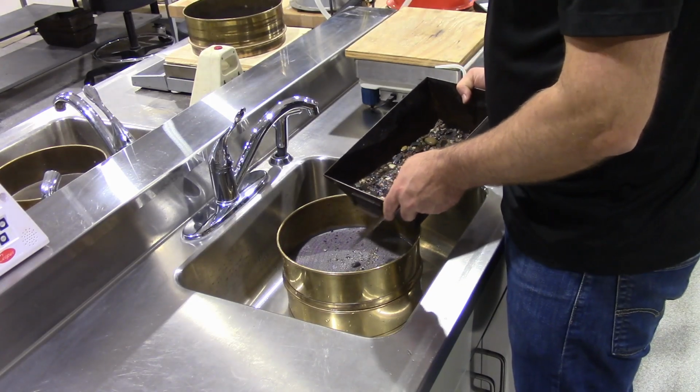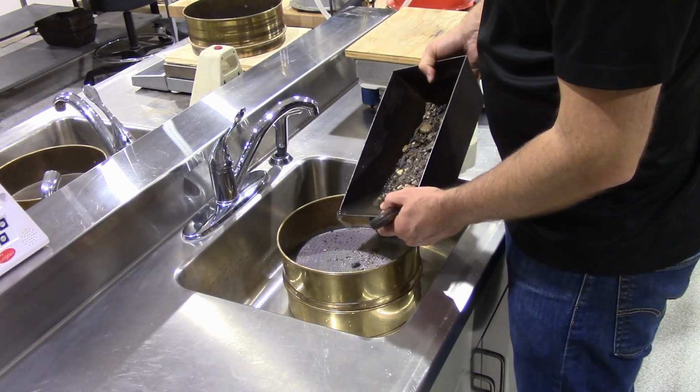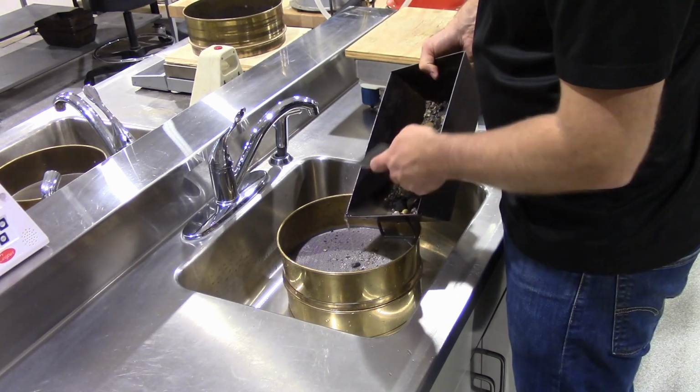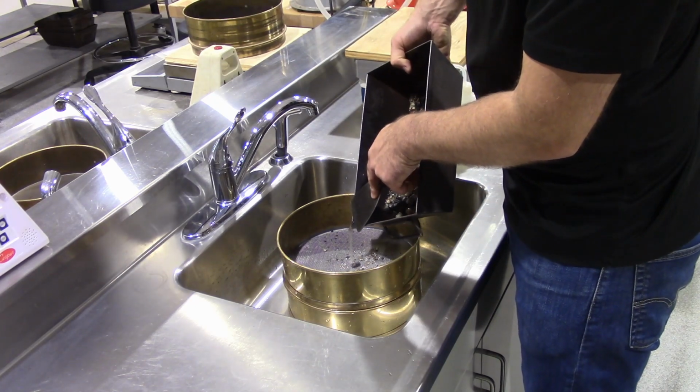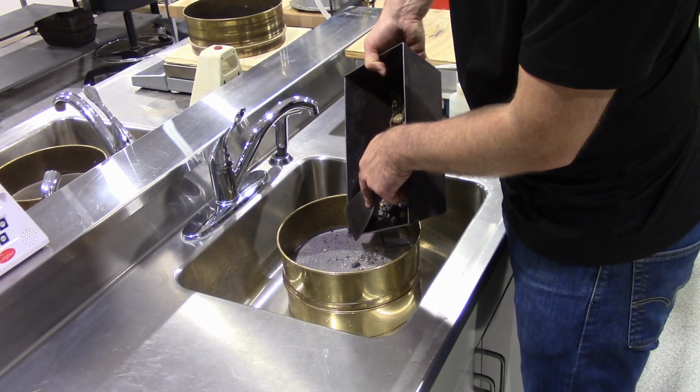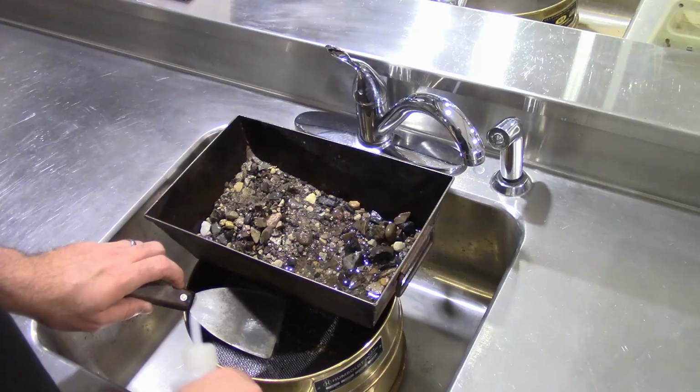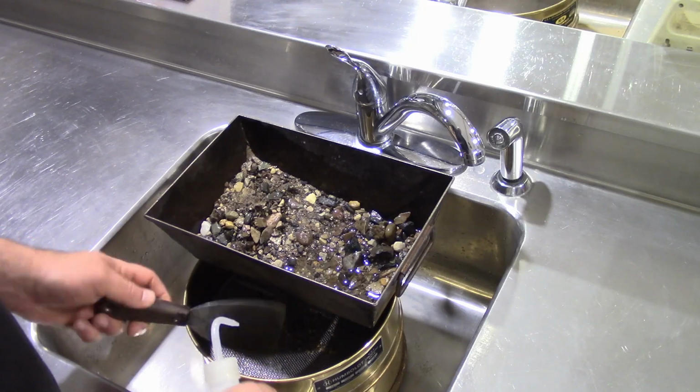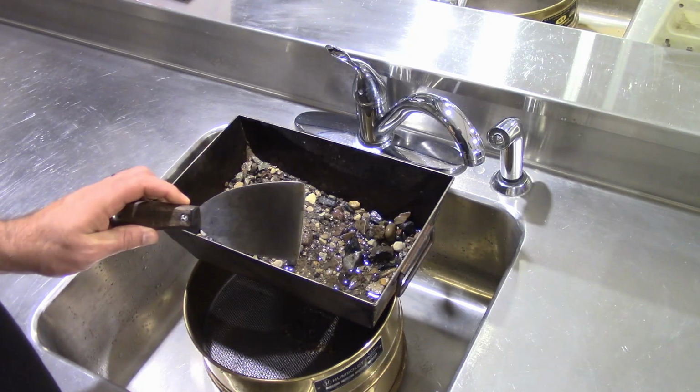Use the tool to stir up all 4 bottom corners when performing this test. Try to decant as much excess water as you can. This will assist in speeding up the drying process. Lightly shaking or tapping the container will cause trapped water to rise to the top of the sample.